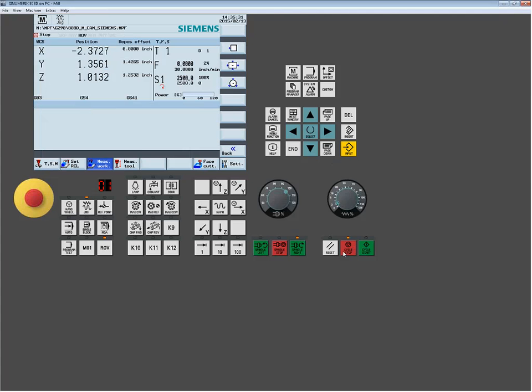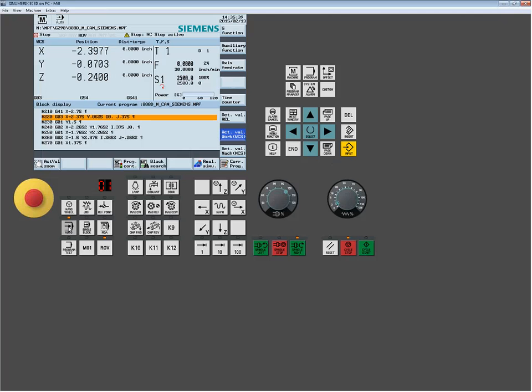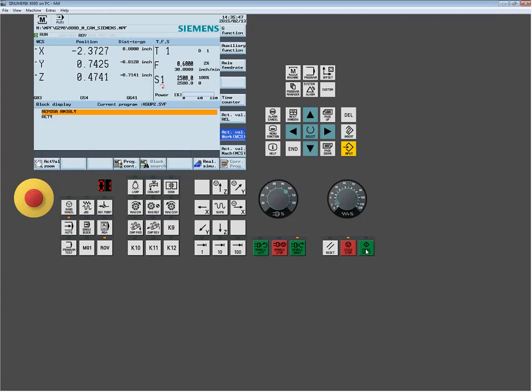Whether I want the spindle and feeds is really up to you. I'm not that concerned because I'm passing them through with R variables. But you don't want operators to have to go into the subs to make any editing changes. The only area they should go into, if any of them, would be the main program file. So I just commented out these lines. If this was a real part that I was going to do in production, I would just delete them. No need to see this kind of stuff.